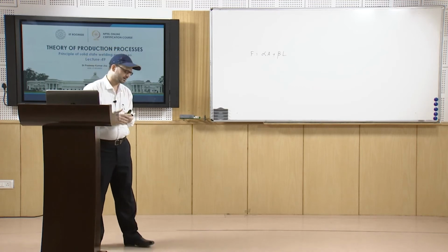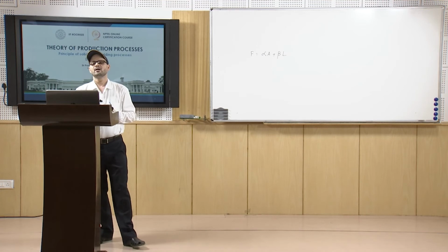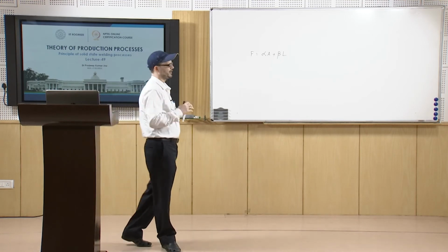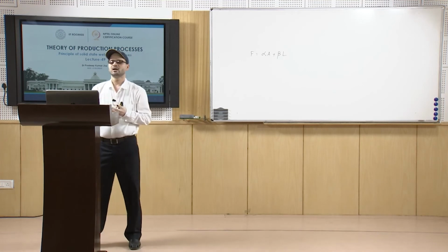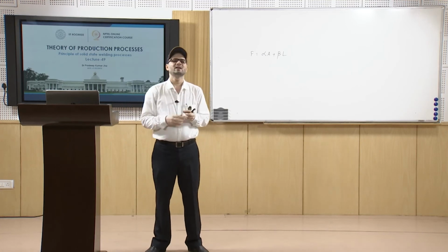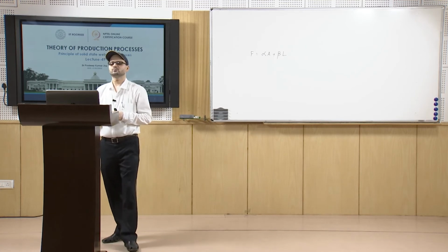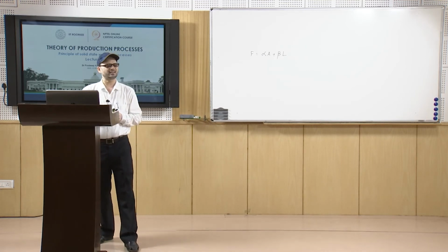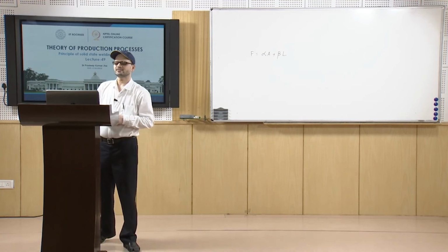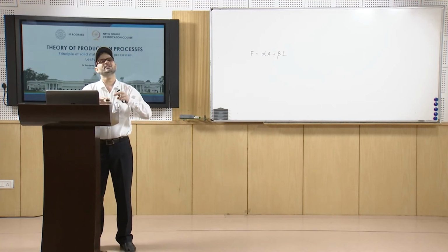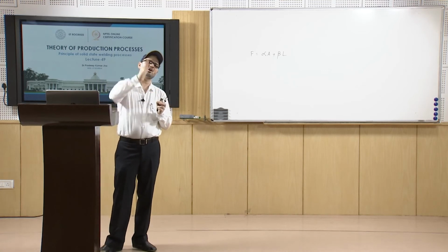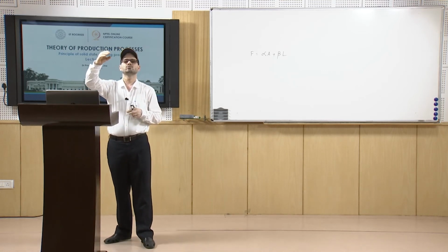If you look at the stages which occur in friction welding, it normally occurs in 4 stages. In the first stage, you have the dry friction when the parts are just touching each other. Dry friction is generated, and towards the end of the first phase the torque will somewhat increase. The second stage is a stage of seizure and rupture, and towards the end of the second stage the torque goes to a high value.